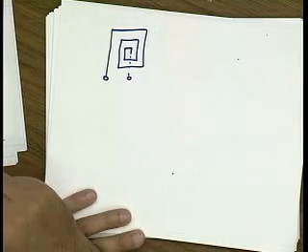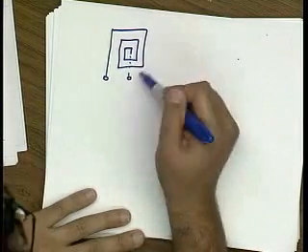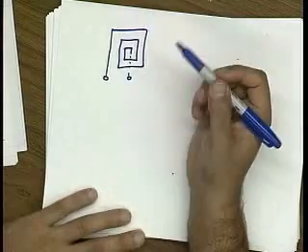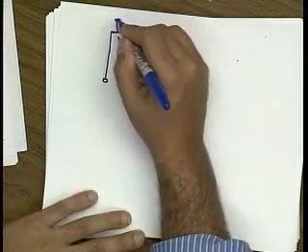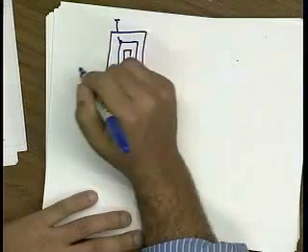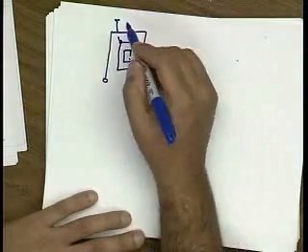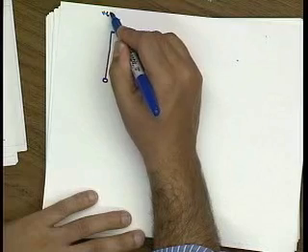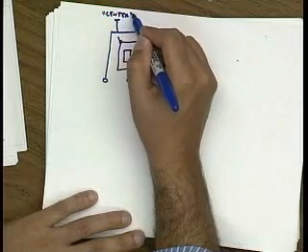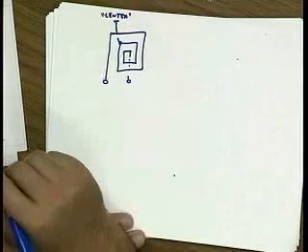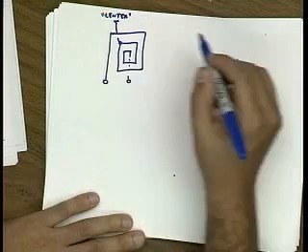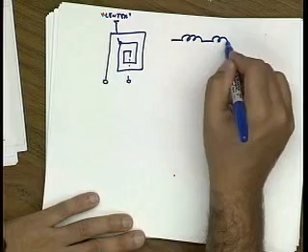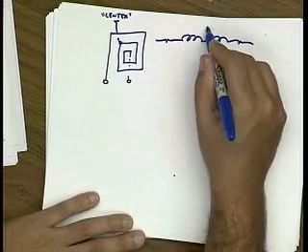Okay? So there's a couple of problems here. First of all, where's the center of the structure? Where do I tap it? Okay? So let's say that you, by trial and error, find the right point to tap. So this is the center. This is the electric center. It's basically not the geometric center of the structure, right? It's the electric center because we want the inductance to be half.